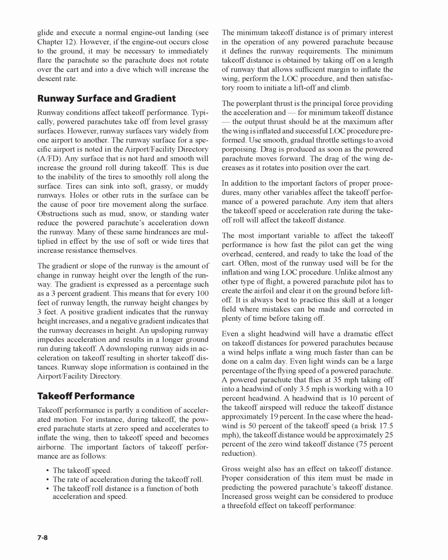Often, most of the runway used will be for the inflation and wing lock procedure. Unlike almost any other type of flight, a powered parachute pilot has to create the airfoil and clear it on the ground before liftoff. It is always best to practice this skill at a longer field where mistakes can be made and corrected in plenty of time before taking off.